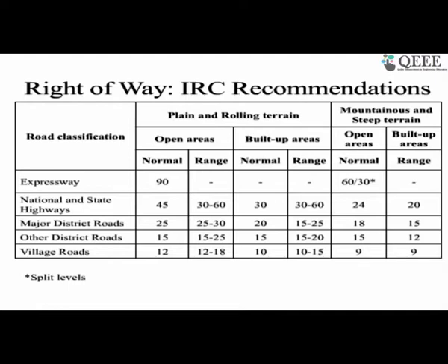And then there are various other concepts of cross sections in the urban setup. Sometimes they provide a green barrier between the travel path and the pedestrian, depending on the width they are considering. The green barrier means they will plant trees and other things, so those need to be considered.